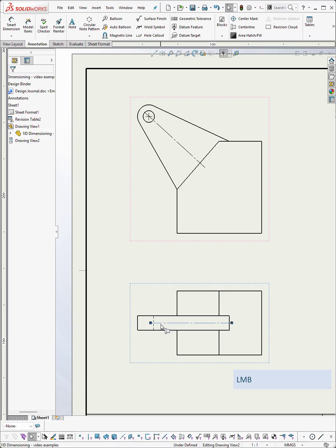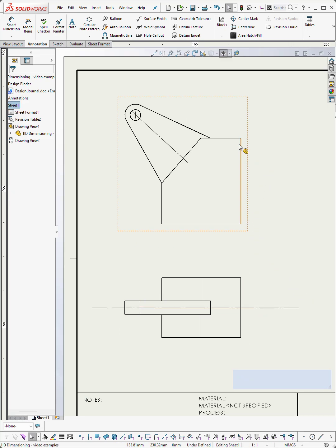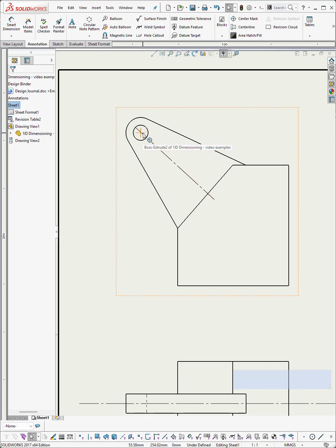And this lower center line will be an axis of symmetry, which we'd normally mark with a CL on either end. We're not going to do that today. So this point here will allow us to infer all sorts of things if we put its position in. So in other words, from that line and from that line, we'll be able to infer the position of this arc and then these angles, because this center line indicates that there's a symmetry around it.